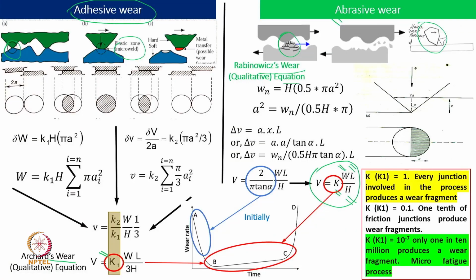And then we can relate both these probabilities, K1 and K, with a wear curve. What we have already covered is the bottom curve, something like A to B, where there is rapid wear, or we say the rate of wear is very high in the A to B zone, and similarly there will be rapid wear in C to D also. While in B to C, wear will be more or less constant, maybe gradually increasing. So naturally, when we talk about the constant K or K1, mostly it should be related to BC, then only will we get repeatable results. Otherwise, we will not be able to get repeatable results.